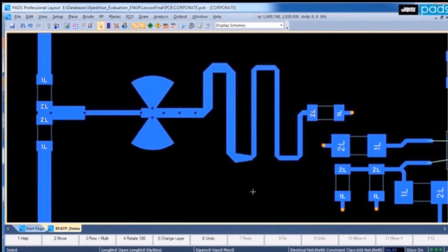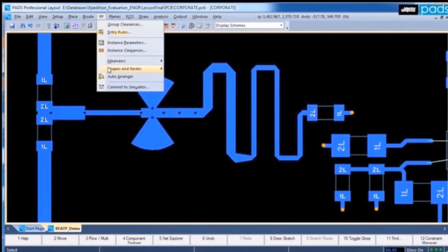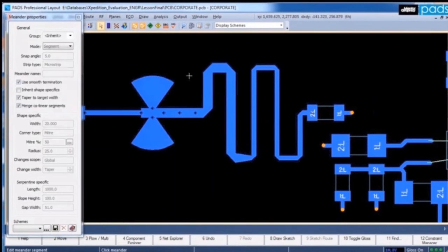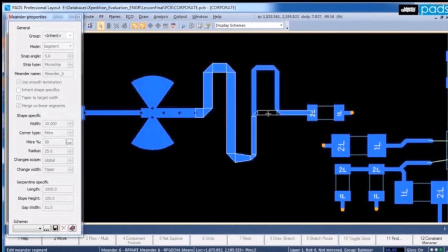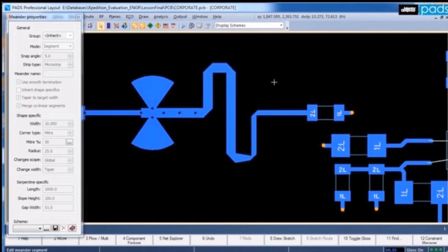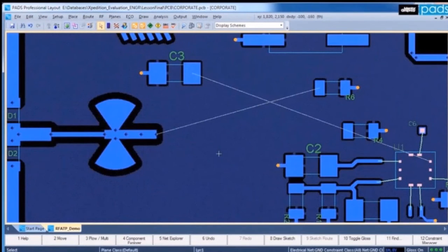To interactively edit the meander, invoke the Edit Meander command and move the segments as you like. When moving segments over each other, the command will snap them into place and remove redundant segments. The Edit command also provides options to lock bends during the edit operation to allow seamless editing of meanders at arbitrary angles. The meander uses the same clearance handling as all other RF elements.